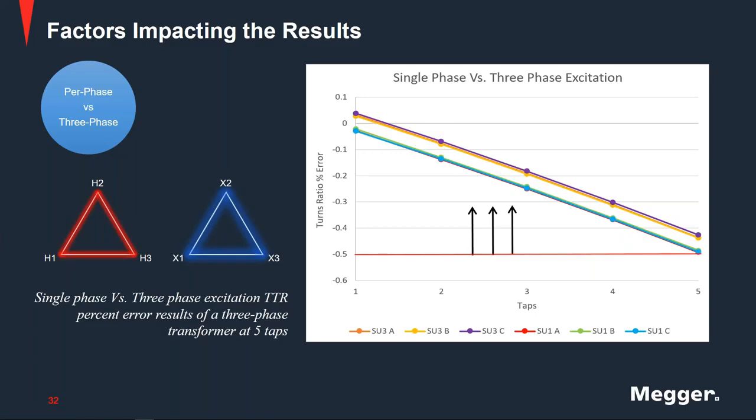So coming to this question of using the auto test voltage mode when you're using the turns ratio test set, the Megger winding analyzer unit has 3 voltage levels: 8 volt, 40 volt, and 80 volt. You can either select any one of those voltages, or you can select the auto mode. When you select the auto mode, the test set would optimize the right voltage that should be used for a certain transformer.